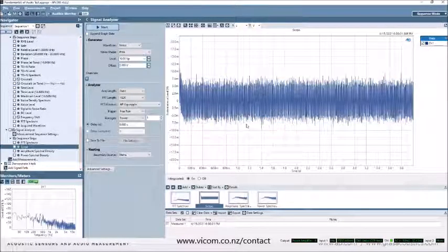So there is an older technique that is a linear continuous sweep where the rate change of frequency with time is constant. The improvement that's been made since then is that mathematically, if you sweep continuously but accelerate at an exponential rate, there's some very interesting things that happen when you do the mathematical transform that allow you to extract the THD data.